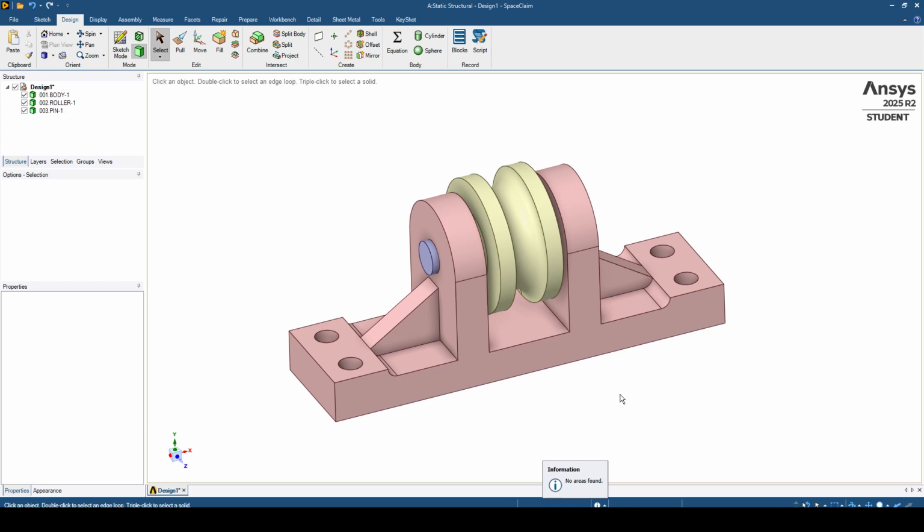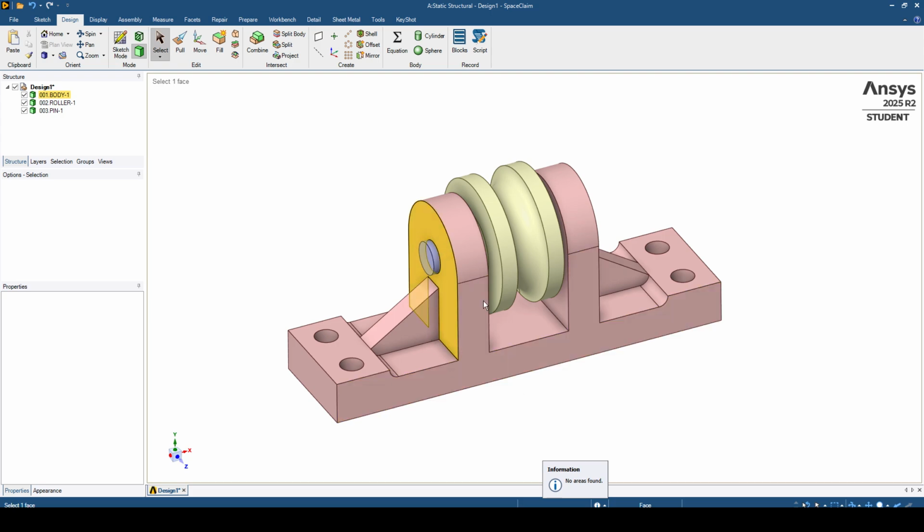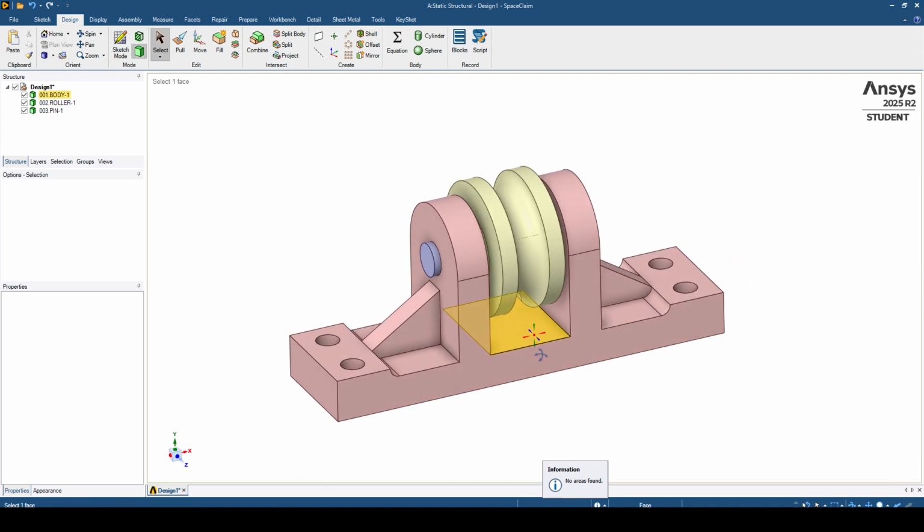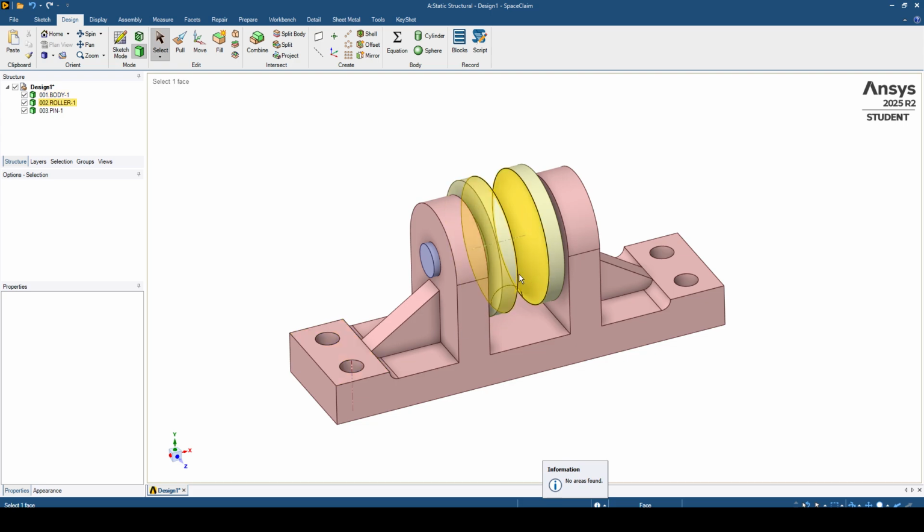So finally, I will make sure the model is clean and ready for the next step. And as you can see, preparing the model doesn't take long, but it makes a big difference. By cleaning all the extra stuff that doesn't affect the simulation or increases the number of elements and nodes without any sense, you can simplify the model by deleting them in this preparing phase in SpaceClaim, and just prepare the model where you are planning to define your boundary conditions, like support location or the location where the load will be applied and so on.